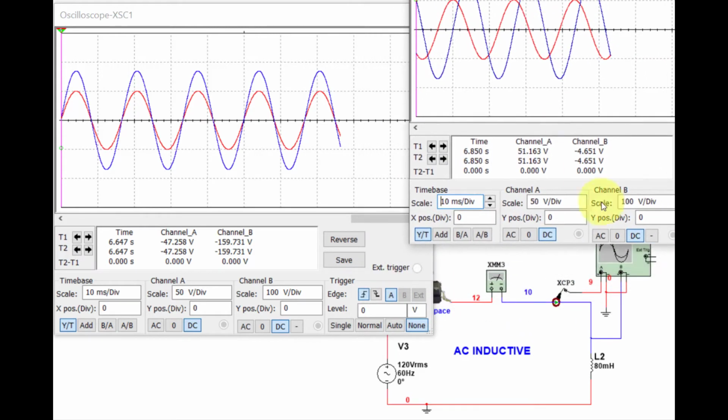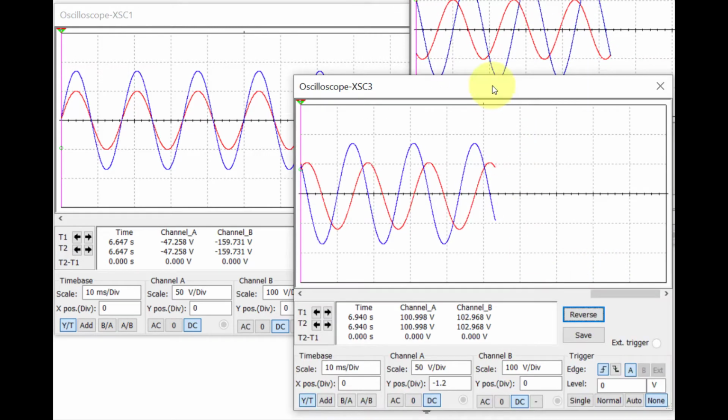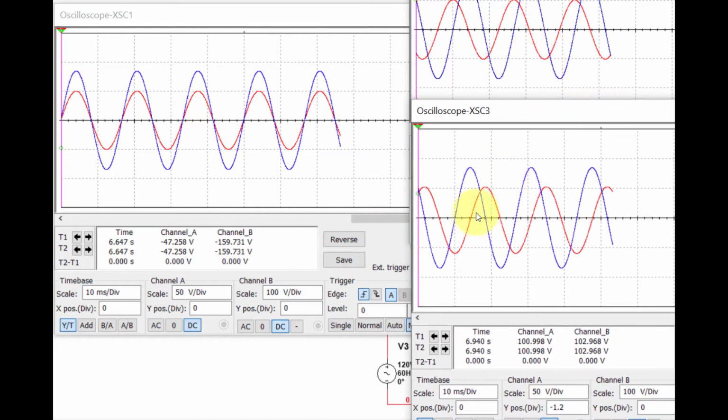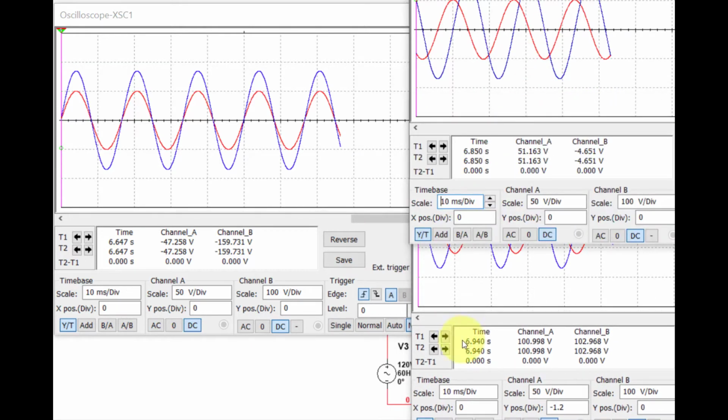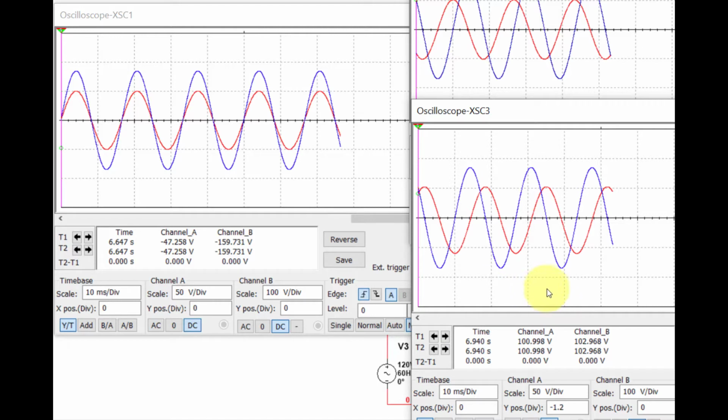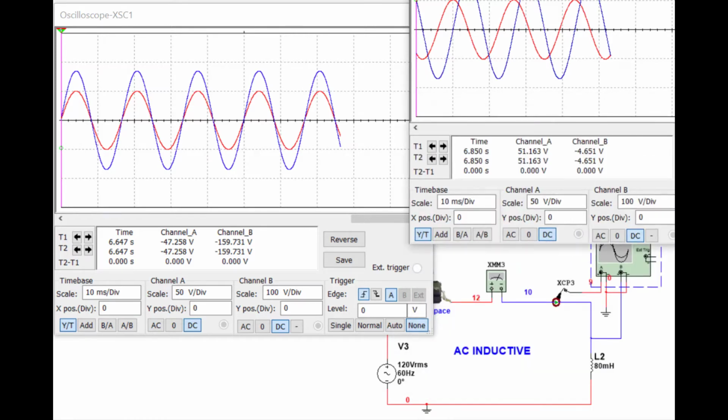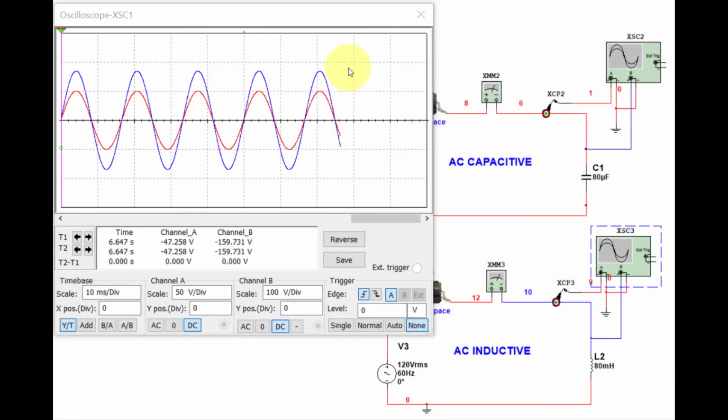All right, so I'll set up the 3 different scope meters and you can see the different signals. I don't know if I can overlay all 3. Yes, I can. And that is the result of having capacitors and inductors in the circuit, and you can only see that with an oscilloscope. You can determine the phase angle between the two, and then you can correct it using power factor correction equipment. So I'll close this up and we will move on with the industrial scope meter exercise.